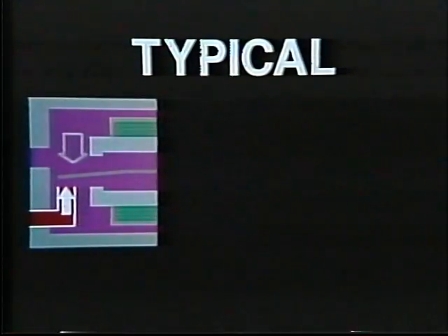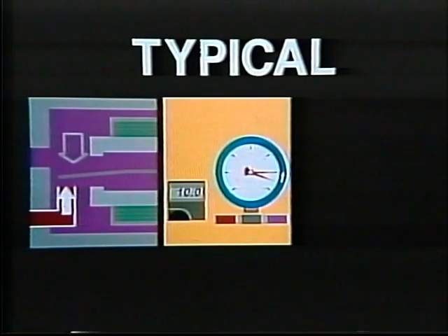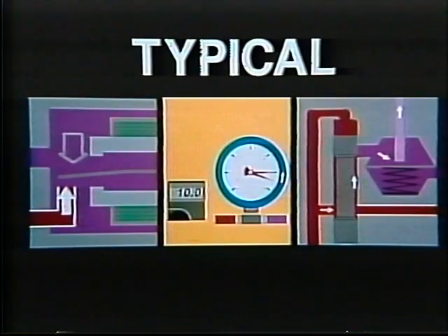See if you can put it together. For typical warm engine operation, the valve is pulled close to the inlet with about 10 milliamps. This causes a small pressure drop between system pressure and lower chamber pressure. The drop on the gauge is about 4/10 bar. Injected fuel flow through the slits is normal.